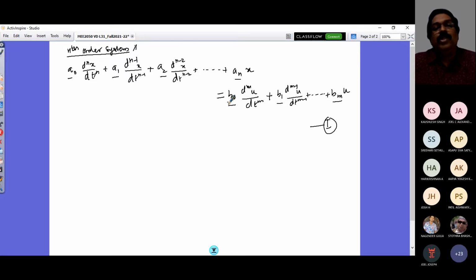To understand more clearly what we mean by a linear system, if I have n number of inputs to the system, then I would have my responses for each individual input. If I add all the individual responses, that would be equivalent to the response to the n inputs together. That is what is called the principle of superposition, which holds good for a linear system. So our study of the bicycle model for airplane stability is a linear time invariant system, an LTI system we call.